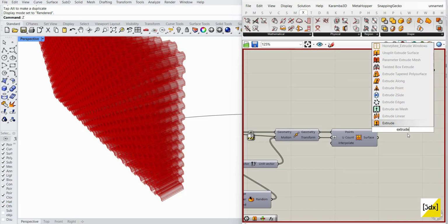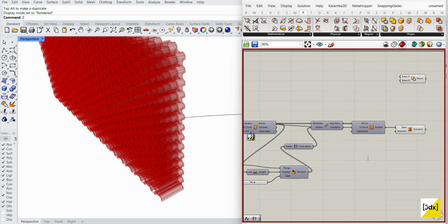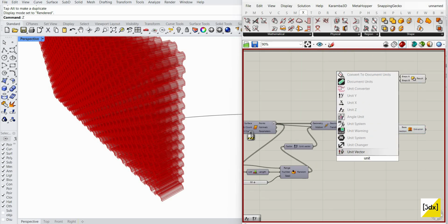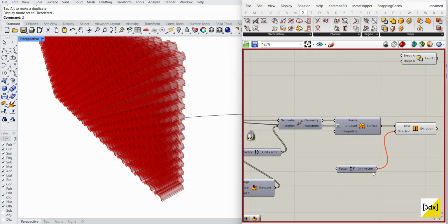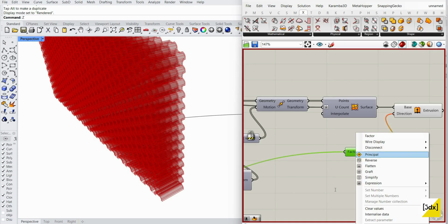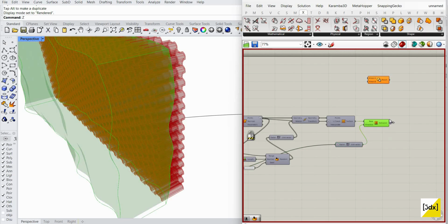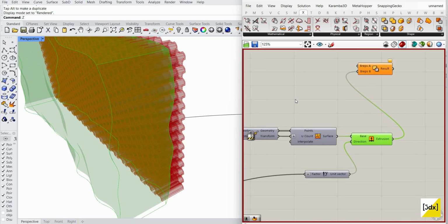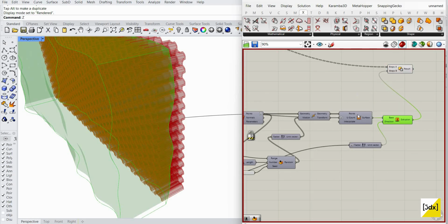So I'm going to extrude this unit y-axis. Let's say like x into 2. Like that. So I just cut it out with the solid which I created with the structure which is already there, the hexagonal thing. So it's a basic Boolean operation.